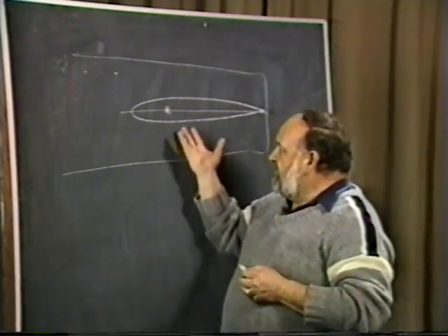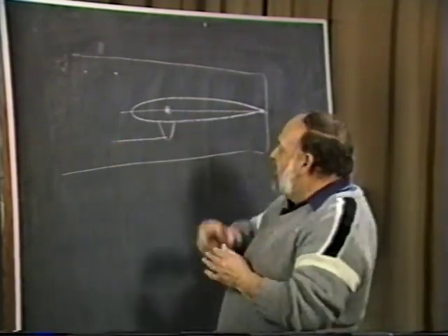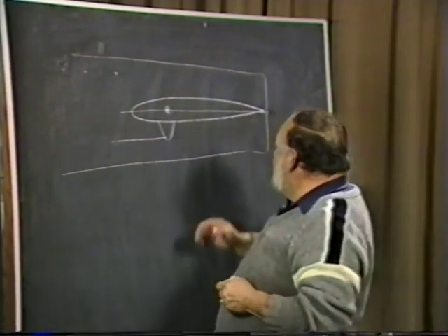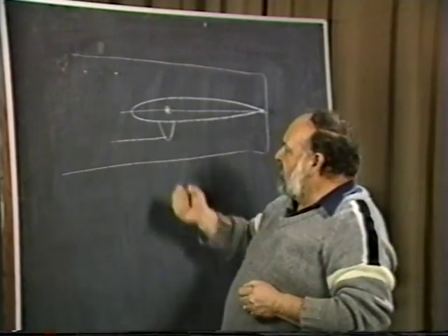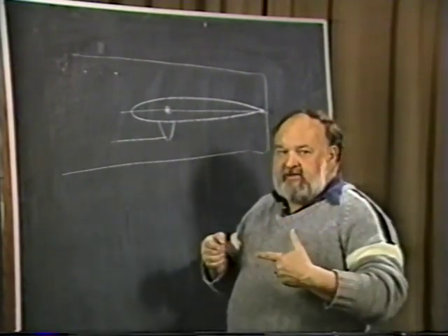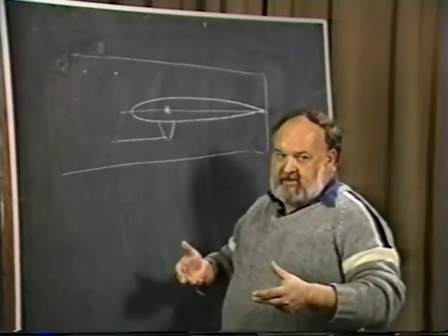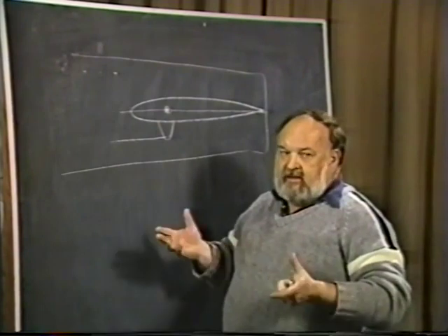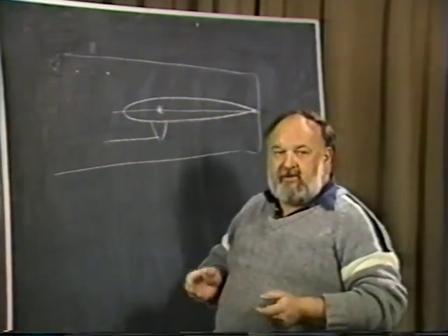But now you have this hooked up to your stick here and you go to move it. Well, you move the surface. If you move it and you have the thing all at quarter chord, you're going to have absolutely no forces within the stick, because a symmetrical surface balanced on a quarter chord can go from 0 degrees to 5 degrees to 8 degrees to -2 degrees, and no hinge moments, no forces whatsoever on the thing. It's perfectly balanced all the time. So you don't like that.